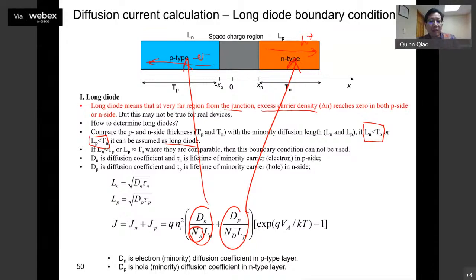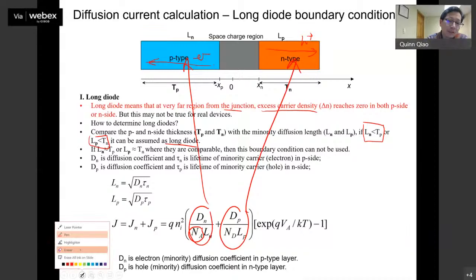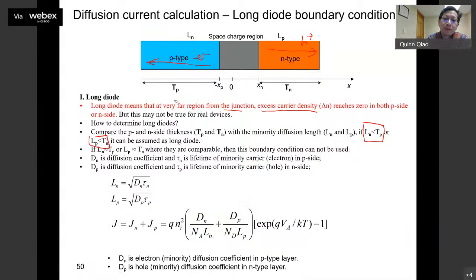I'm sorry. Only the n side has the dopant, because you take a lot of electrons, right? That's the N-type doped. Now on the inside, they have P as hole transport, right? Hole diffuse. That's the diffusion. That's why you have two terms. You have diffusion current for electron, diffusion current for hole. You add them together, right? That will give you what? Give you the saturation current.